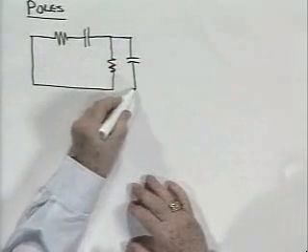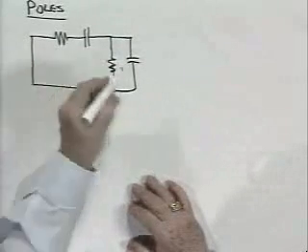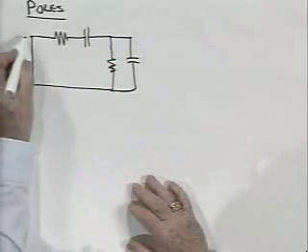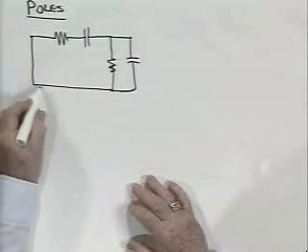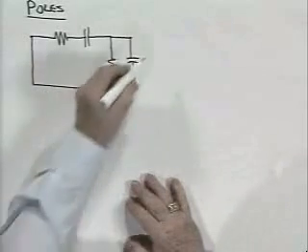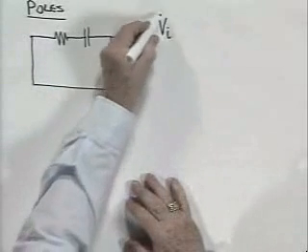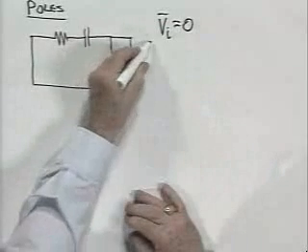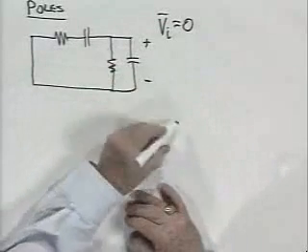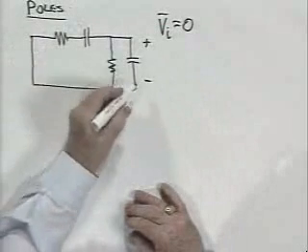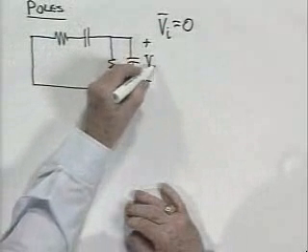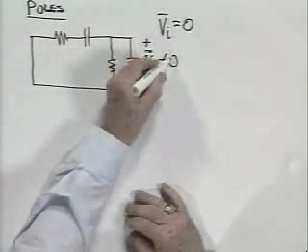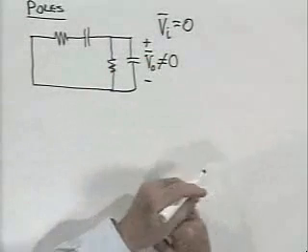So here's the circuit redrawn. I won't label all the coefficients. The voltage V sub I, which we defined here, we're now setting to zero. That is, we're letting V sub I be identically zero. And we know that at certain frequencies represented by the poles, we can still have a V sub O which is not equal to zero. How can that be interpreted?